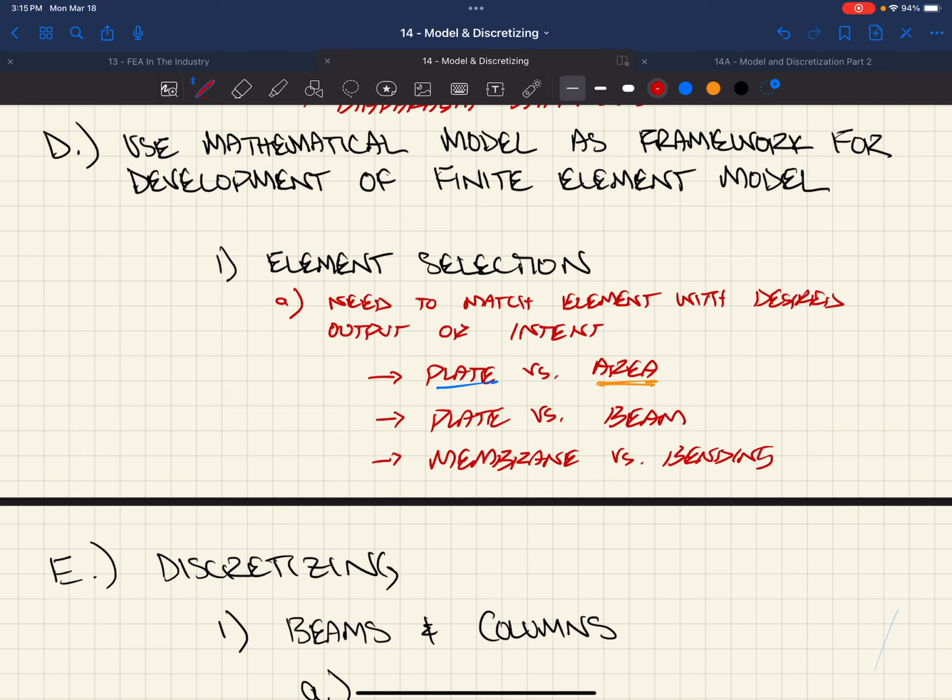Are we worried about our shear wall taking out of plane loads, or can we just model it as a membrane element, right? I think it just depends on that shear wall configuration and the building design and things like that. If it was a shear wall that took exterior wind pressures, then I would say yes, probably want it to be a bending and membrane element. But if it's an interior shear wall and maybe it stops at the ground floor, there really isn't much internal pressures applied to the outside or to the sides of that wall. Maybe you could get away with just assuming it's a membrane element. That's going to be the dominating demand on that element anyway.